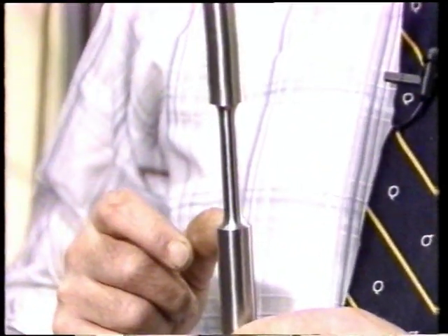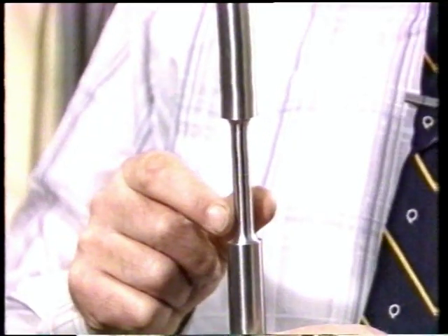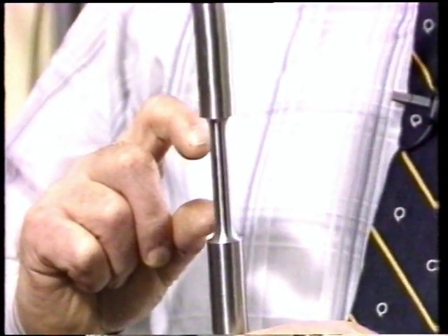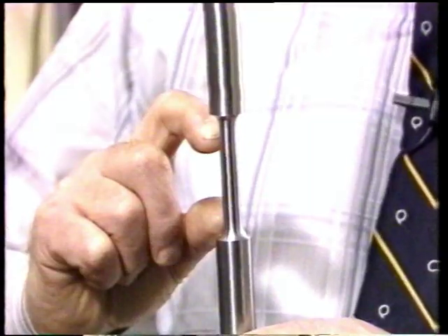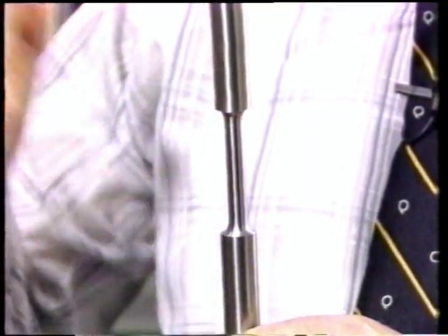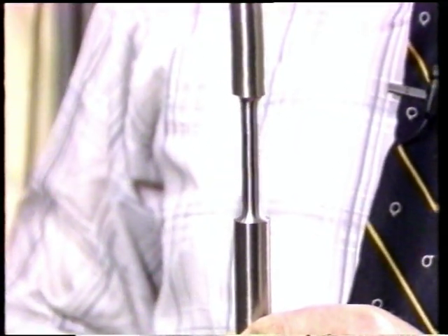Of course, before doing the tensile test, we have to measure that area accurately, and we also have to put some marks on if we want to measure the elongation after the test. It's no good making those measurements after we've deformed the metal.